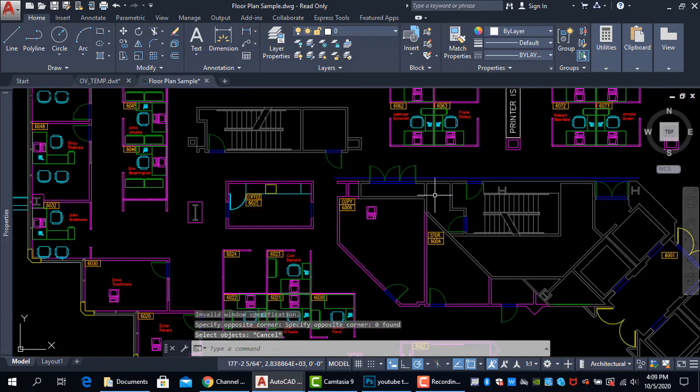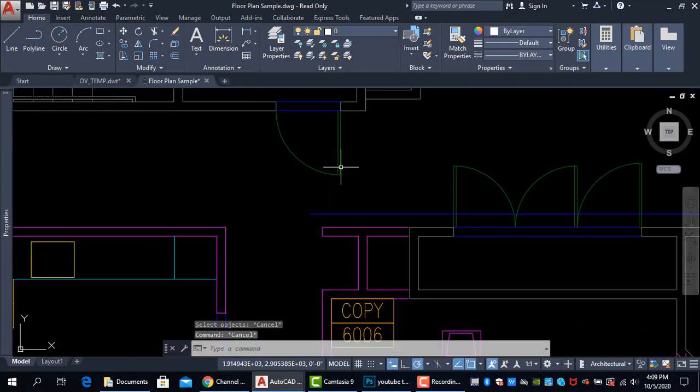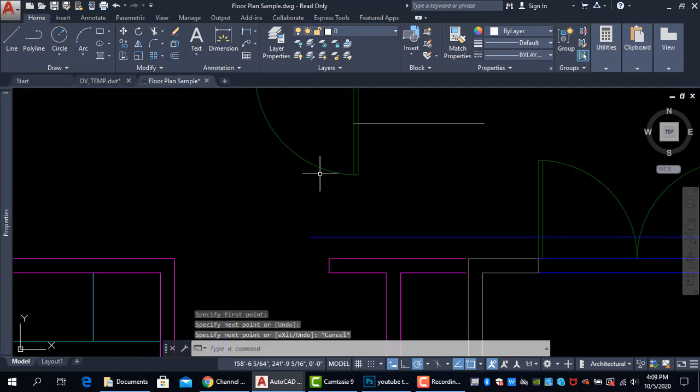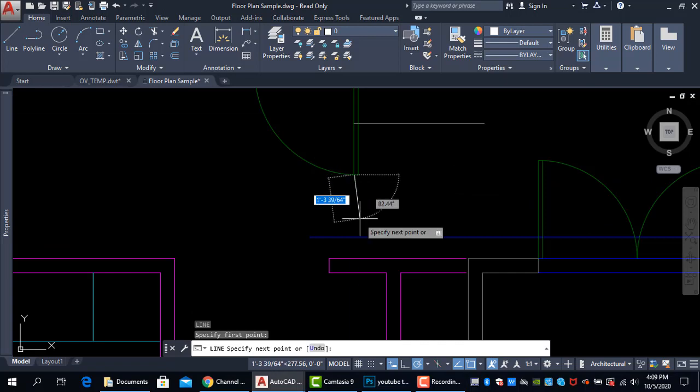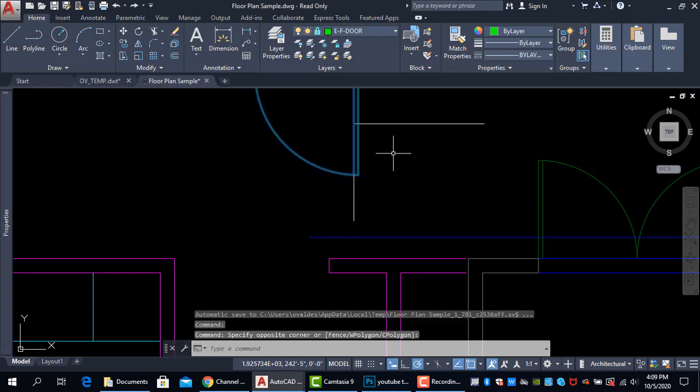So when you have something like this and you want to make sure that some of those components don't move, of course you draw them on the appropriate layer, and then you can lock that layer so you don't mess it up later on, okay? Now, when it's locked, you can still use it. For example, I can still have access to the midpoint. So it does give me some options here, just that I cannot do anything with it.